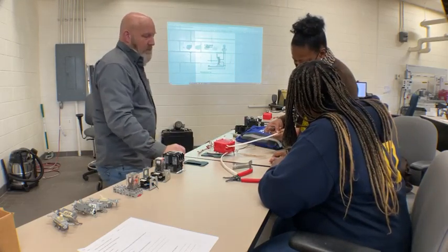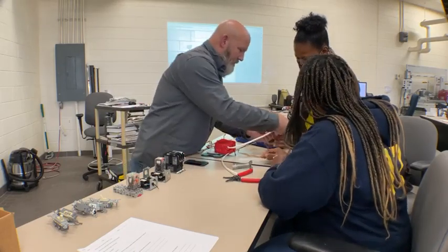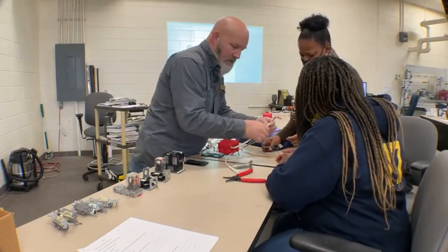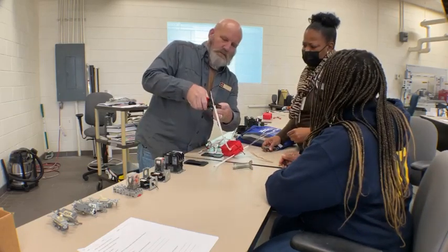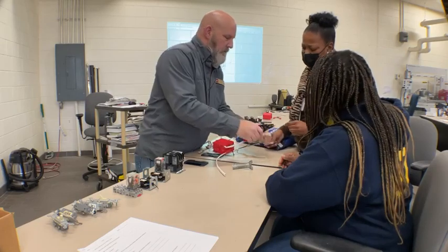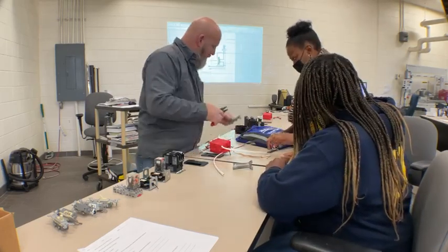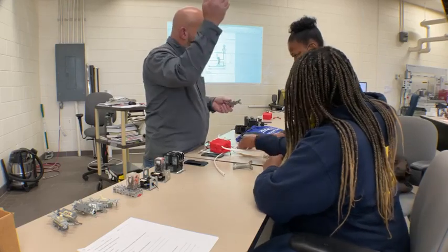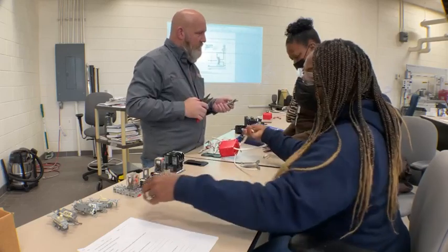Oh, okay. I'll be doing some stuff around the house. And then you pull this off and just cut that off with your cutters. And connect the black to the black and white to the black. Well, you wind the whites together. The black would go to your switch, then the other black would go to your light. Power coming in goes to one, and power going out goes to the other.